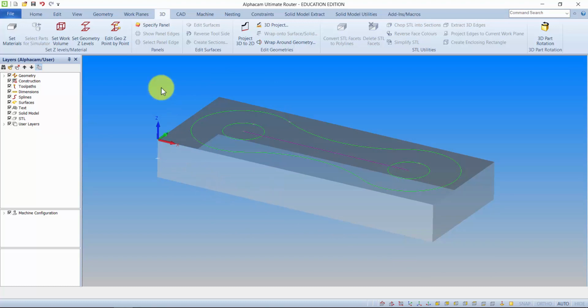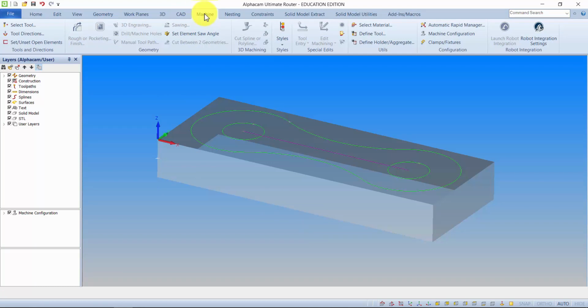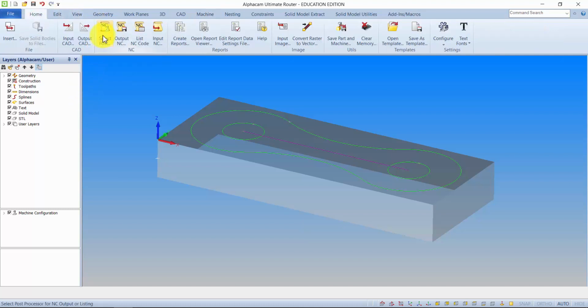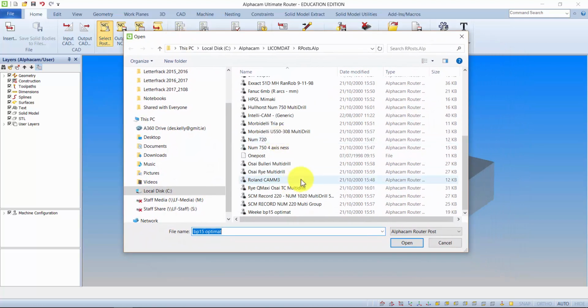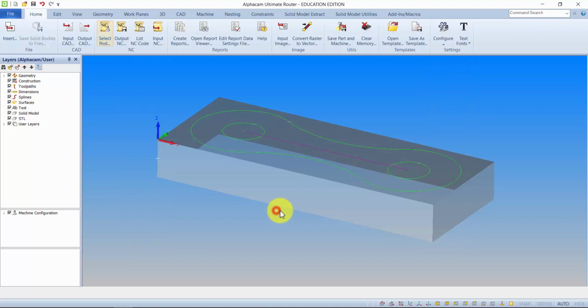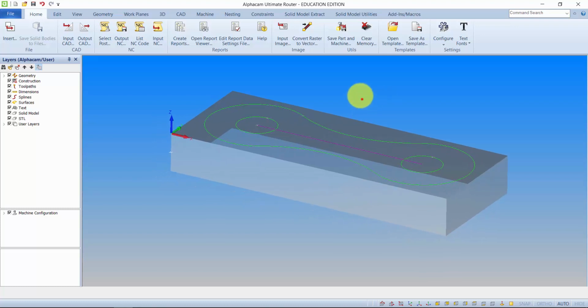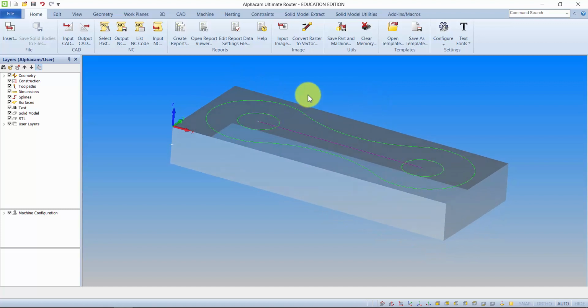So what I'm going to do is go to Machine. The Machine tab is where a lot of the machining options will be, and you'll see there's a lot of them grayed out for the minute. What you could do at this point actually is go to Home, select Post, and that's kind of like selecting your printer. So you can go and see which of the CNC machines that are currently loaded here suit you. I'm just going to pick the wiki here at the bottom, and that now loads that machine. It loads the post processor or the machine into this file. So it knows now what the capabilities of the machine are. You don't always have to do that. Let's get back on track.